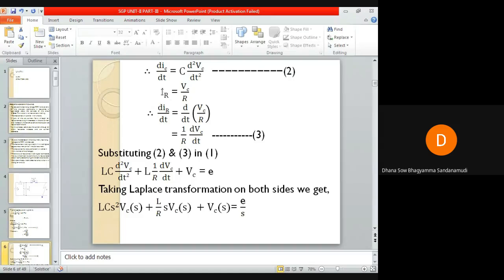And what is IR? IR is voltage across the circuit breaker contacts by resistance R value. Voltage across the circuit breaker contacts is nothing but voltage across the capacitor. So IR is equal to VC by R. So again differentiate IR by dt. So d by dt of IR is d by dt of VC by R. You will get 1 by R into d by dt of VC.